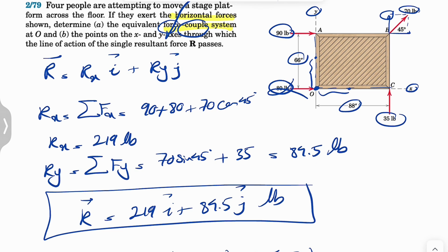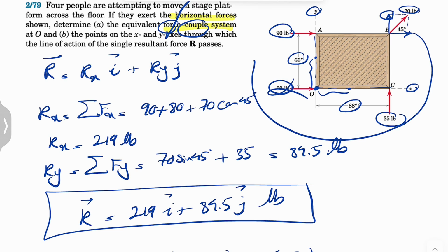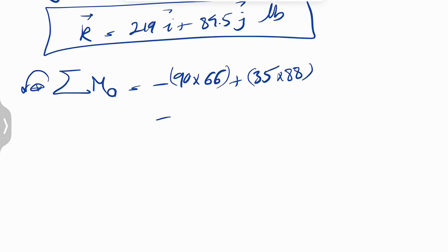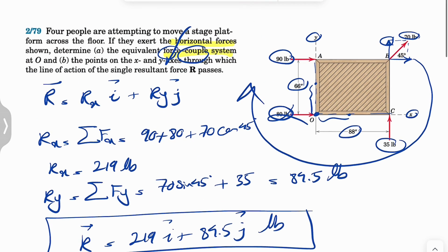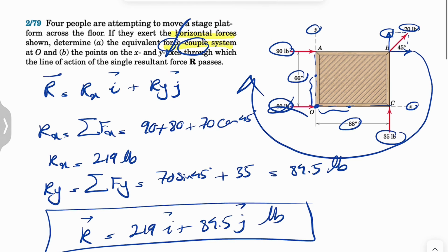And we have the moment of 70 pounds, so we're going to go with the moment of X and Y component. Let's do the X first. So the moment of X is clockwise, so negative. We figured the force is 70 cosine of 45 degrees. And the good thing about the angle of 45 is that the value of the sine and cosine is the same, so it really doesn't matter if you mess up with the angle.